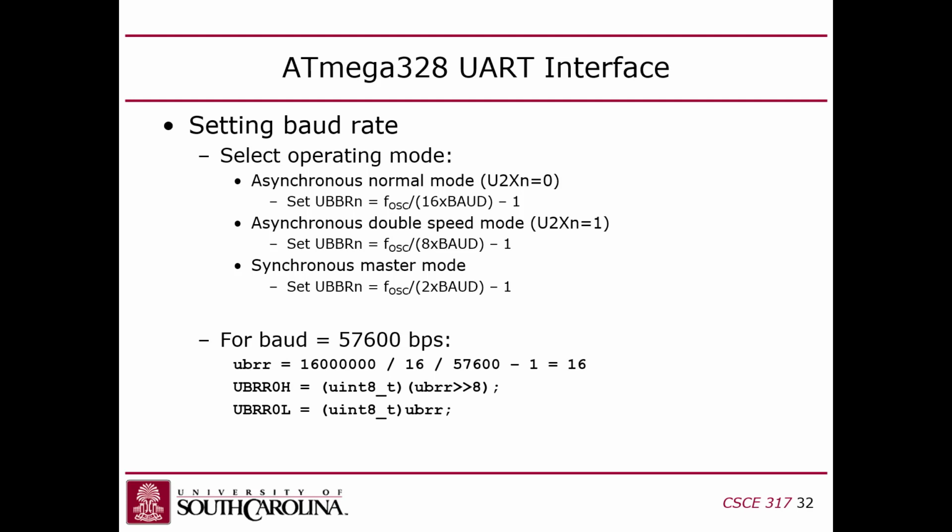So something like the stop bit might be a symbol. Yeah, well, that's what I'm saying. It's including all of the overheads of the protocol. It's the rate at which all the bits are sent. The official definition will say symbols is in the numerator. So symbols per second, inclusive of all the overhead characters, all the overhead symbols or bits.